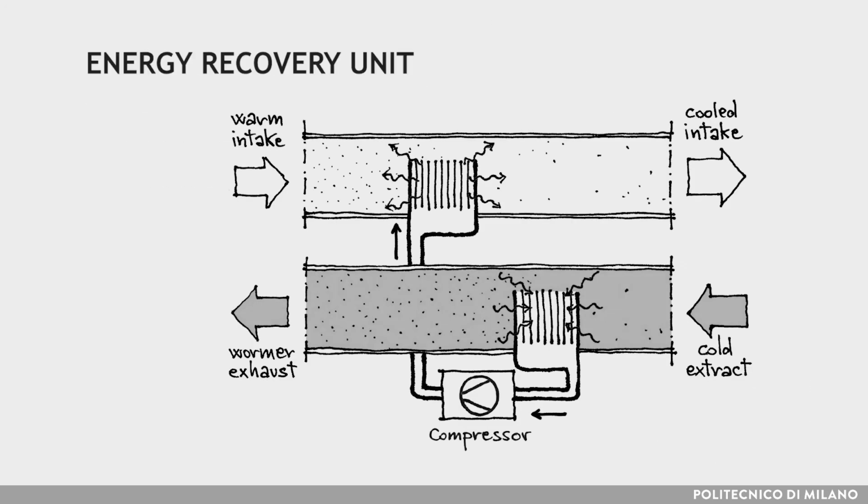To increase energy efficiency, an energy recovery unit can be added to the air handling unit. It is a type of mechanical equipment that allows a sensible and/or latent heat recovery from the exhaust airflow, for example using a vapor compression cycle.